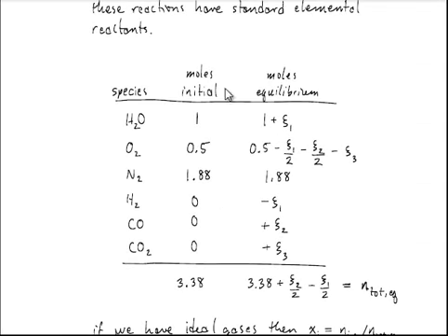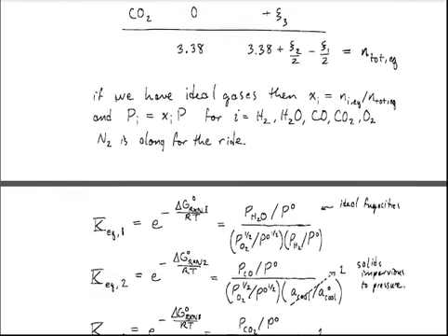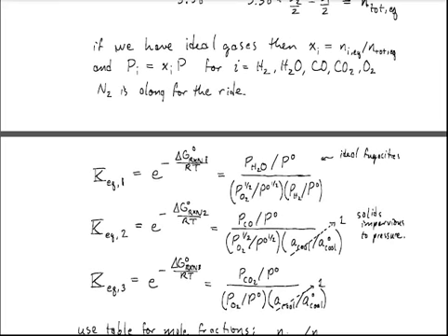So the extent of reaction variables that I'm using here, by the way, can have signs that are positive or negative in general, and that's one thing that makes them a little bit more of a mindless approach than dealing with fractional conversions. With fractional conversion, you often have to identify your limiting reagent and work with the fractional conversion of that limiting reagent, instead of really being able to just allow the math and the optimization to find the appropriate values and signs for each of the variables. So from this point on, it's really a matter of going through and plugging everything in.